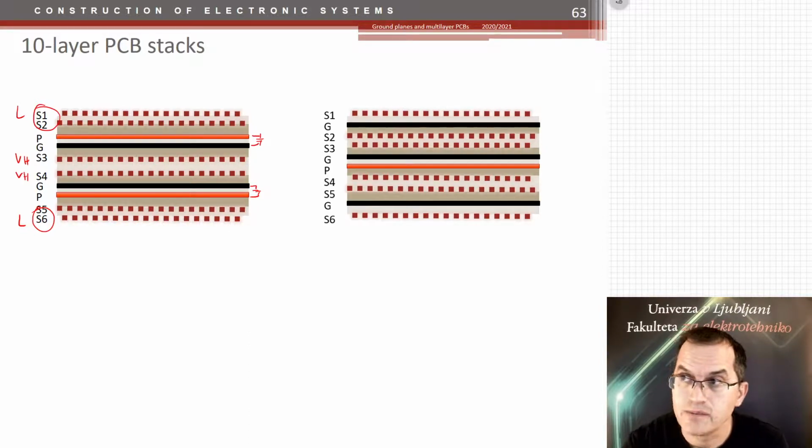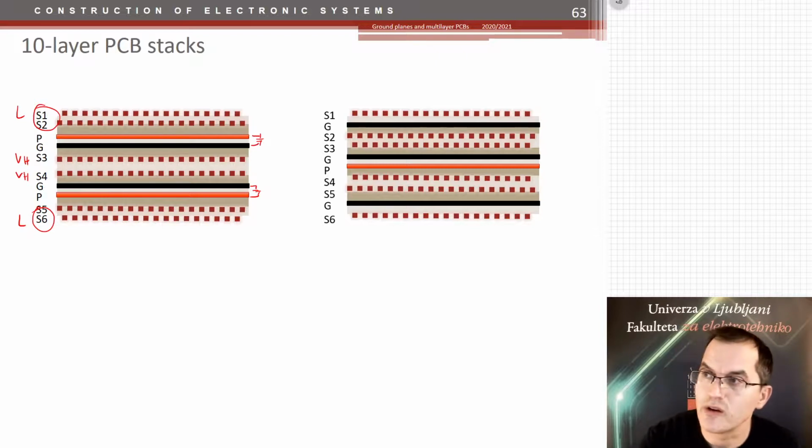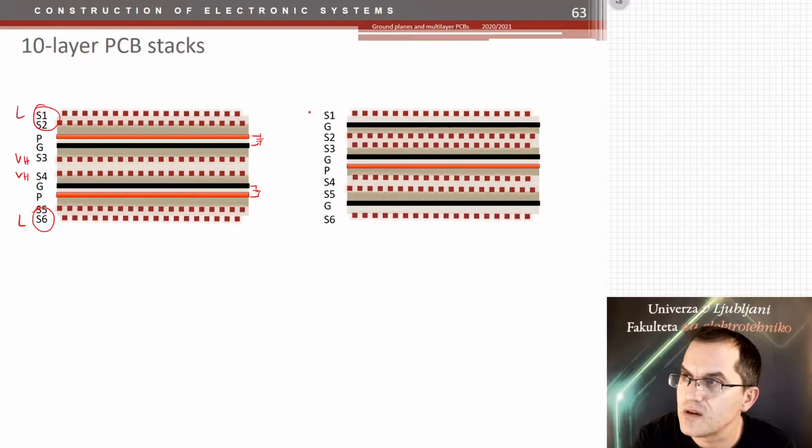But if you have them, then you have to use more ground planes, at least 3. Well, 3 ground planes would mean then you have high-speed signals here, very high here, very high here. Please note here we have to use interleaving or different orientations to minimize the coupling. Here is a nice capacitor. Then we have low speed signals there, and then we have again very high and high speed signals there.